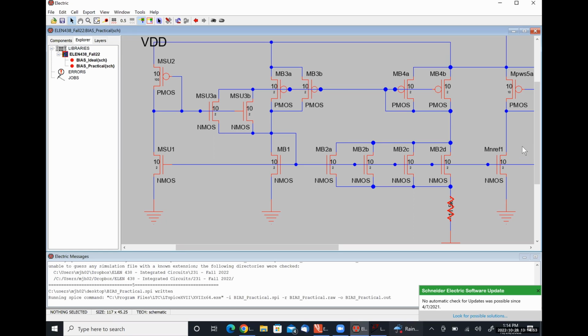I think they do a better job of preventing me from making all these unnecessary pins. It's the order in which you place the elements and then make the connections. If you put down a transistor, make yourself a little stub of wire, put down ground, and then connect that little stub of wire to ground, you've created an unnecessary pin, because you didn't wire that terminal of the transistor directly to ground using a single piece of wire.